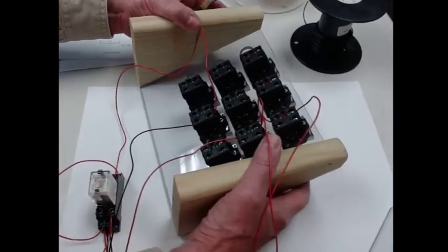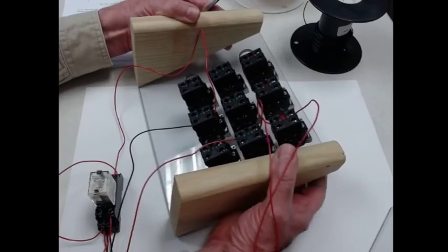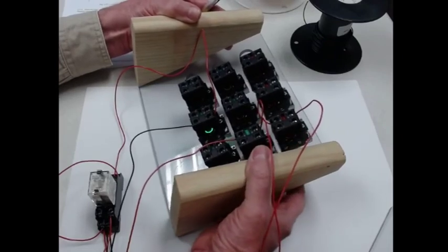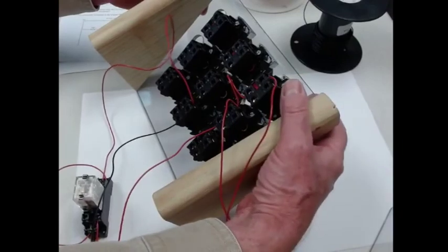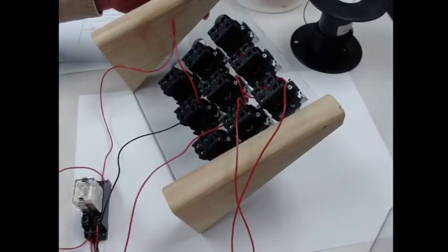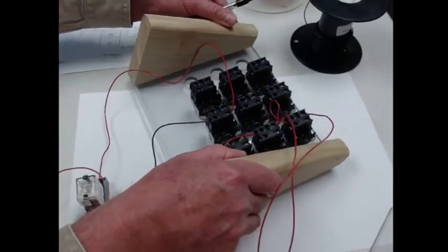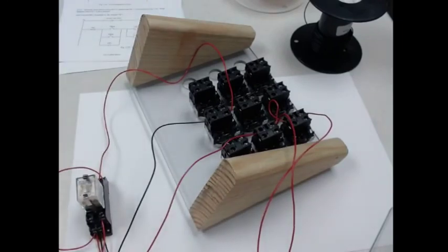So basically what we've done is we've given an alternate path. So if I push my stop button, nothing happens. I push my start button, what happens? The relay turns on and the light lights. If I hit the stop button, it turns off. And that is a seal circuit. That's a memory circuit. That's the simplest memory circuit that you can have.